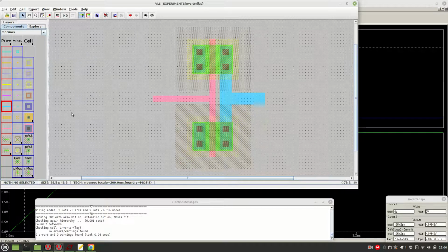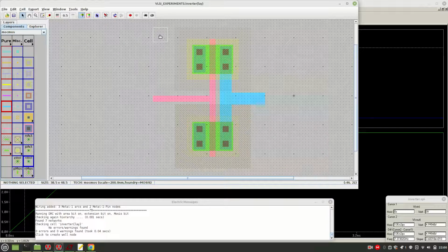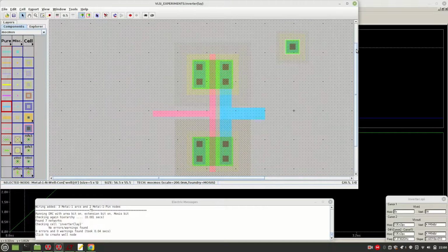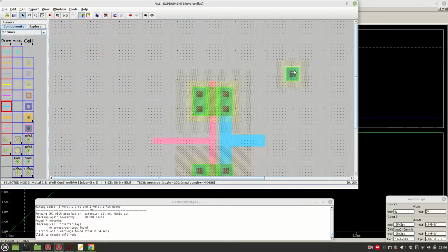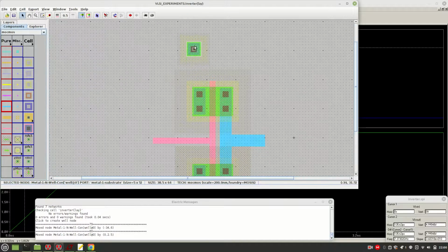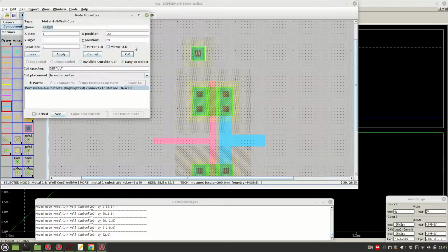So for that, this is the Pmos, so you just need to add the N well for this one. So we need to go above this, and this region has to just touch this region. Or else just increase its width to 10, 5 or 10, anything is fine.